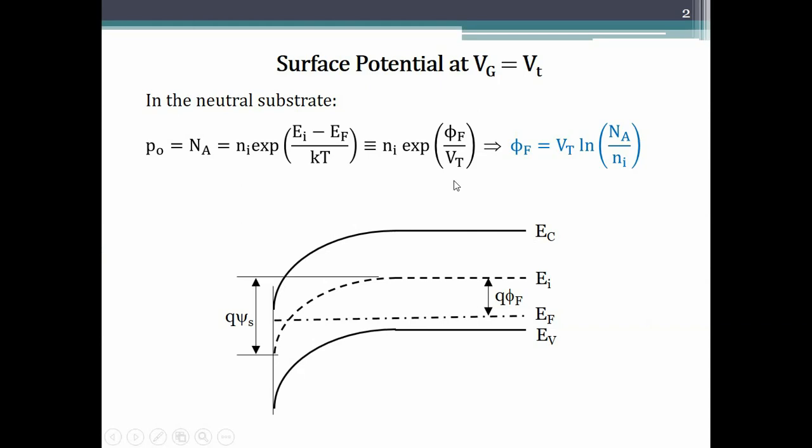Okay, so here is what is called a band diagram of a MOSFET. On the right hand side is a p-type substrate, and on the left hand side is when one approaches the semiconductor surface. So this thin line is the semiconductor surface, and when a gate voltage is applied, the bands bend down. This is drawn for a p-type substrate, and so the Fermi level is closer to the valence band. And when a positive gate voltage is applied, because these are electron bands, they bend down. And there are more and more electrons, which is indicated by the conduction band being closer to the Fermi level. Okay, as I said, if you don't understand any of this, don't worry about it.